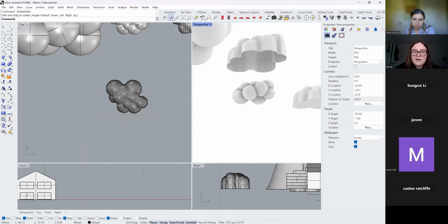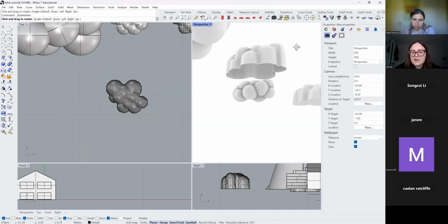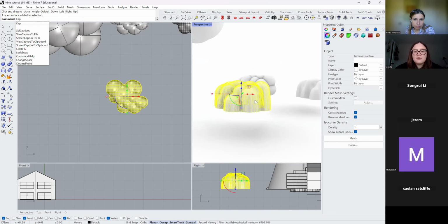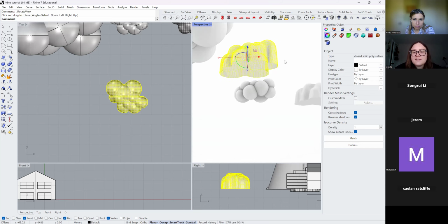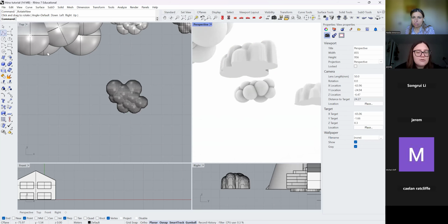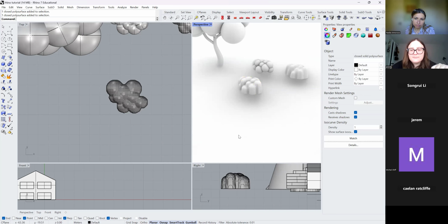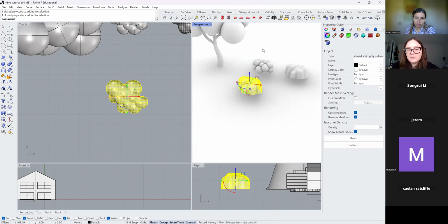If you have any poly surface that you're trying to have closed, what you want to do is click it and type in cap. Okay, and then you can see now that this bottom part is closed. While people aren't seeing it because it's on the bottom of your model, it's something you should know about in case you have something on the surface that you don't want people to see in. If it's a planter, that's great, you can keep it open, but if you don't want something that's open, you just cap it.